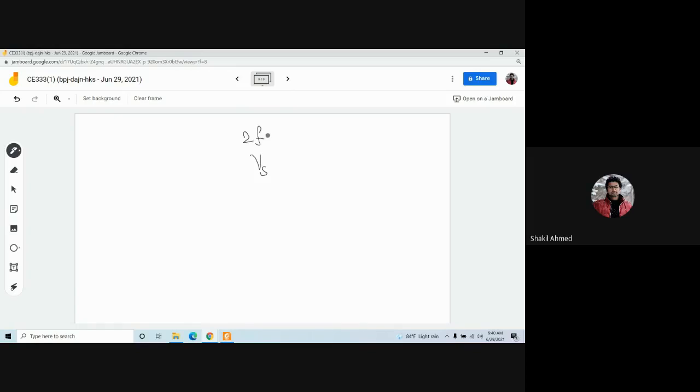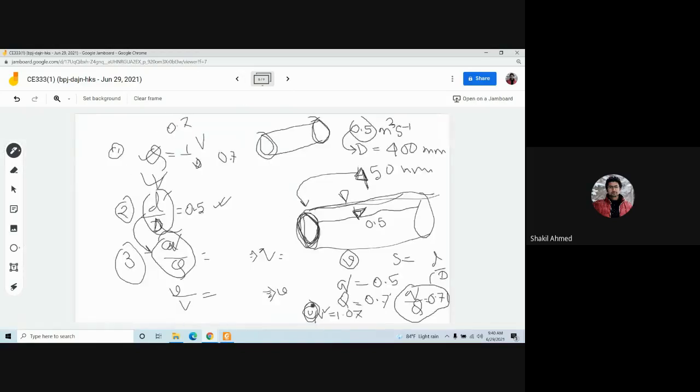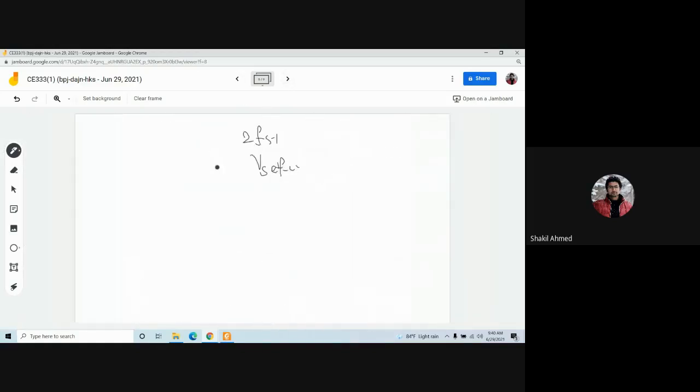the self-cleansing velocity, remember? Around 2 feet per second. Self-cleansing velocity, remember that? And your small v has to be greater than or equal, right? Yes, sir. Otherwise, it will not be able to clean the debris.